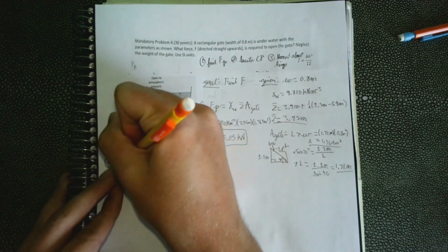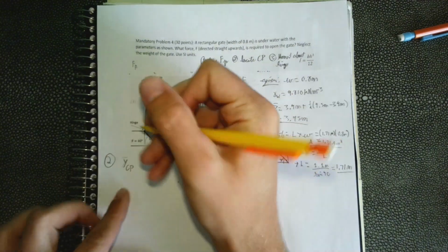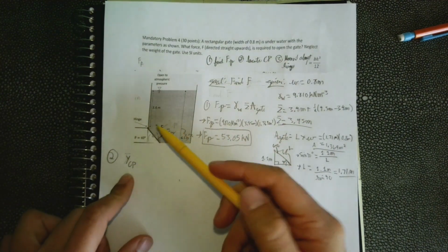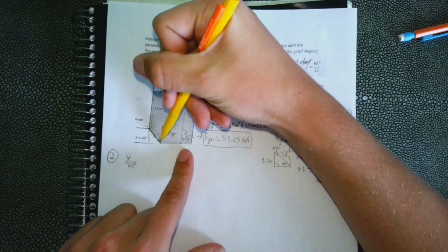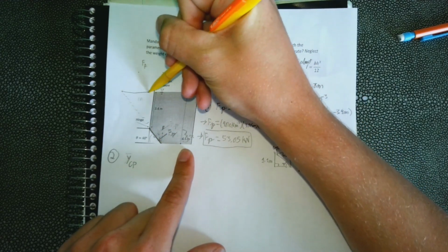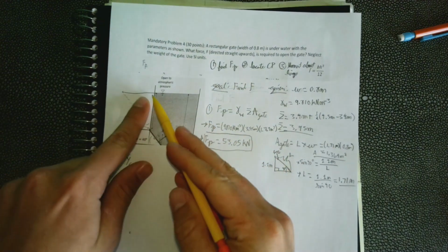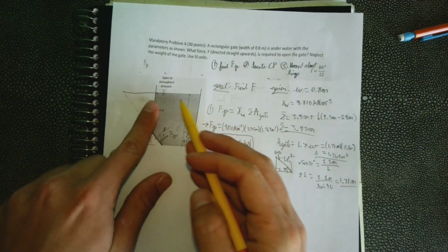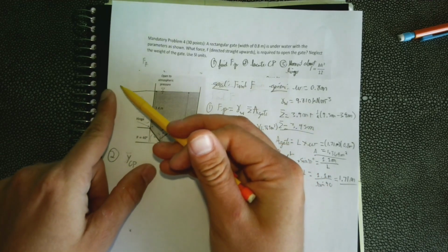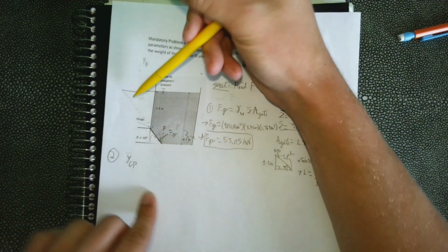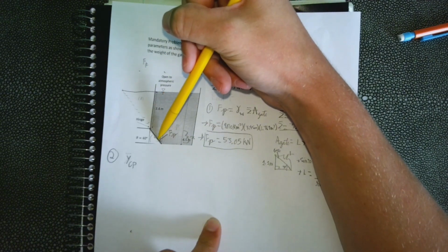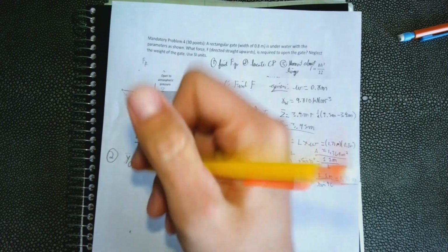So it says slant distance for the center of pressure. And remember that slant distance is, if you continued at this angle to the surface of water, so this is the surface of water, and this is the slant distance, right? So it's saying that we're finding this slant distance at this 40-degree angle to that center of pressure. So that's what that is.